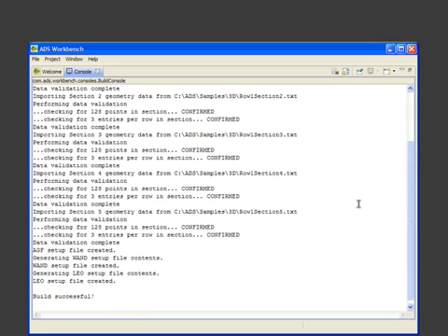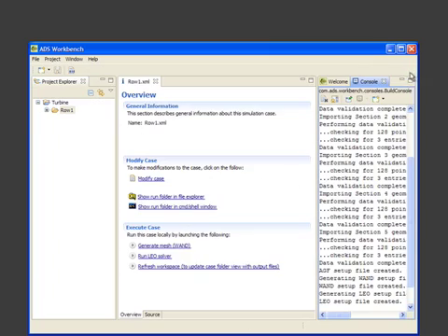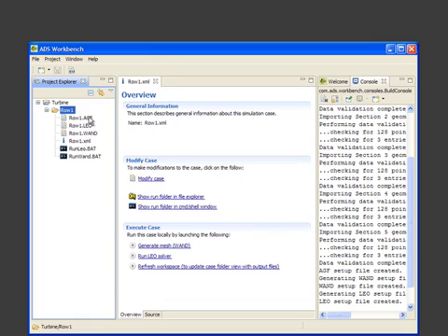Let's go back over to the Project Explorer, and you can see now under Turbine there is a row 1 directory with several files that have been generated underneath that. There is a .agf file, a .leo file, a .wan file, and 2 run scripts, runleo.bat and runwan.bat. If you are running Linux, the runleo.bat command is actually runleo.sh, and the runwan.bat is runwan.sh.